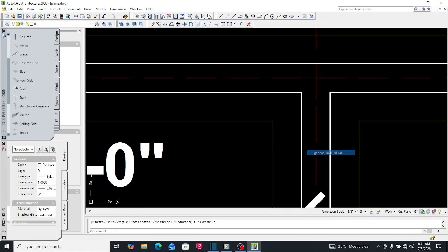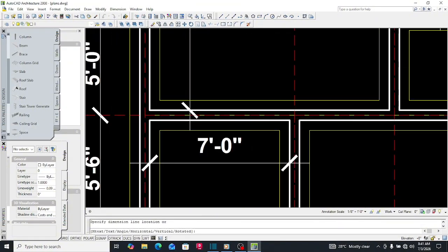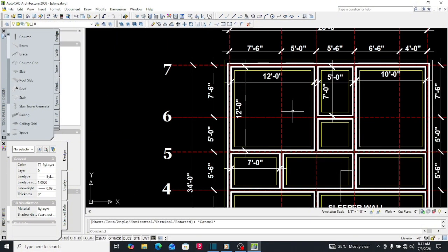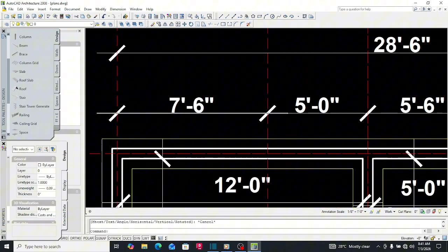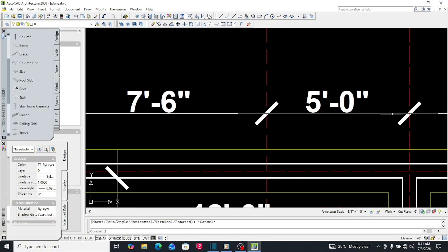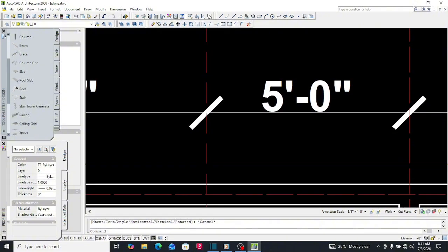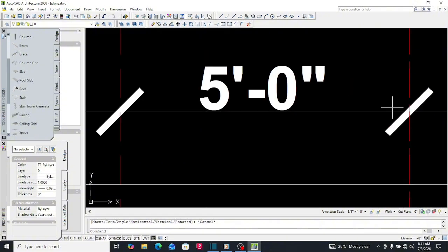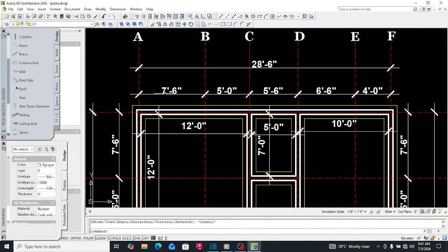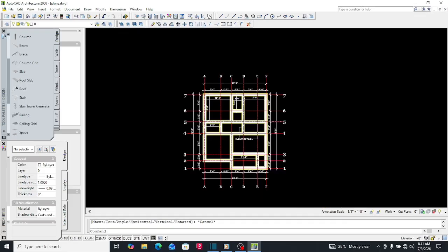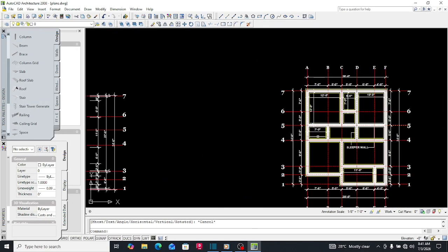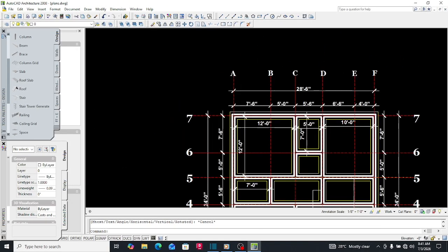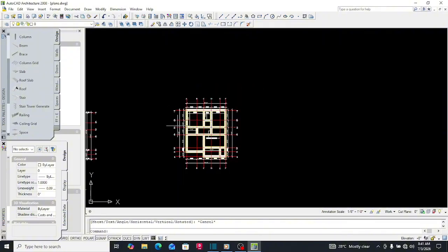You still stand on it, you measure to this side, you have to get 9 inches. Then after doing that, you measure from here to here 5 feet. You put the nail on the board, you do the same thing. So you'll be doing the same thing all on the board where you are seeing the A, B, C, D, and the 1, 2, 3.